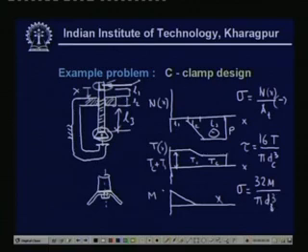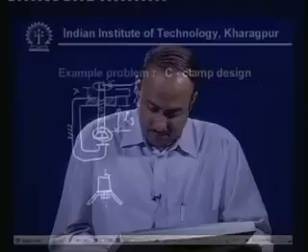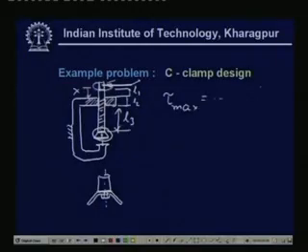So, there are different kinds of stress available here. Now, you have to use the failure criteria and get the correct value of dc, that is the root diameter of the thread. Now, there are a few failure criteria which you have. Say we have tau max, this is the failure by maximum shear stress, and this will be equal to sigma.